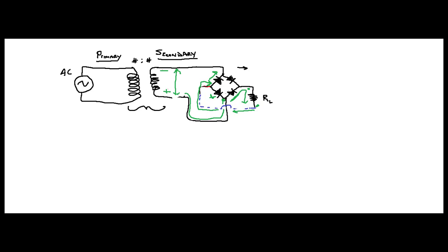Well, remember, this voltage right here at this point, you just got to follow your voltages and think about it. We just finished saying that this voltage here is one diode drop, but then it went one diode drop lower than your potential here. And then it went even lower here, so this is a lower potential, and it dropped again right here. So this voltage is at a lower potential, so this is reverse bias. It's not going to go there again. So that diode is off. So it only has one choice. It's going to come back this way.